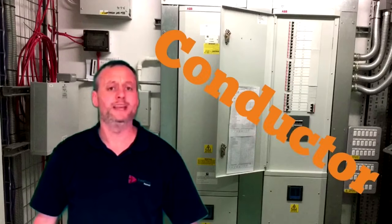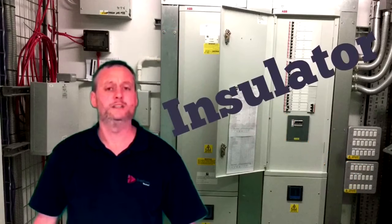On the back of looking at the construction of an atom, we said that if a material had a free flowing electron in the outer shell of its construction, it's likely to be one that can be a conductor. If they are tightly bound electrons, we said that is likely to be an insulator. We went on to look at the most common conductor material being copper, silver possibly being the best one used widely within the electrical industry, but not selected for cables due to the fact of its expense.